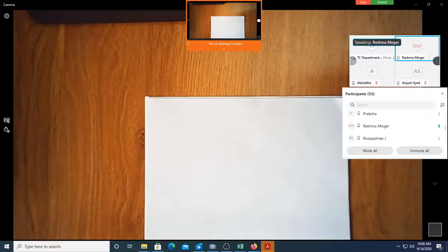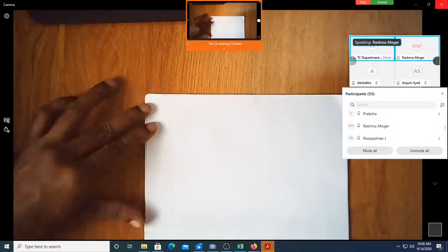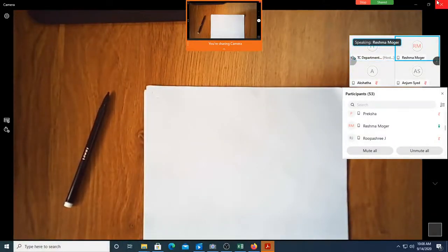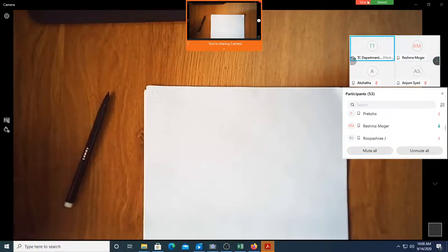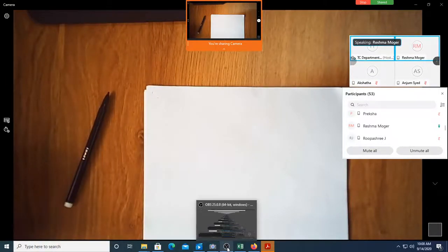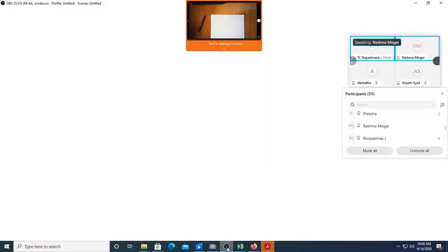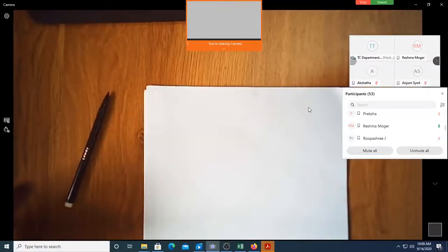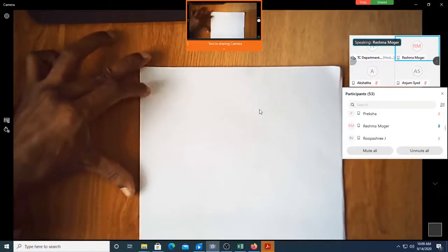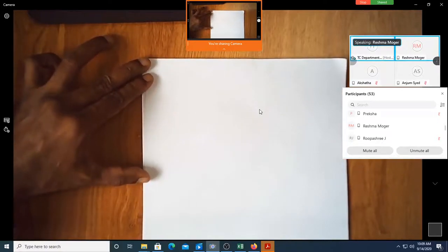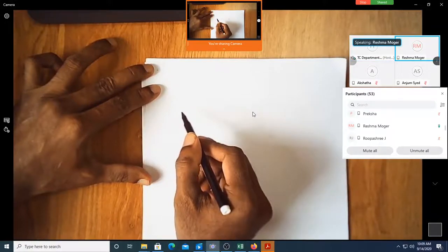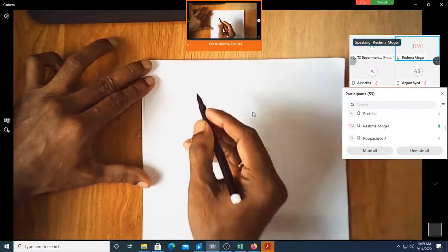Working of MOSFET, sir. Okay, MOSFET exclusively, what phenomenon? Pinch-off phenomenon. Basically, that is for what purpose? Okay, when will pinch-off occur and all those things? When the drain to source voltage equals the saturation voltage, pinch-off starts.